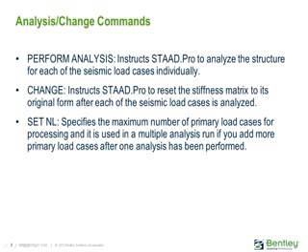We have one more critical step to complete our process for generating our seismic loads for our sample model. We should add a few commands into the STAAD.Pro input file, which of course we can do through the graphical user interface. We should add a perform analysis command after each of the basic primary seismic load cases. This will instruct STAAD.Pro to analyze the structure for each of the seismic load cases individually. After the perform analysis command, we should add the change command as well, and this will instruct STAAD.Pro to reset the stiffness matrix to its original form after each of the seismic load cases is analyzed.